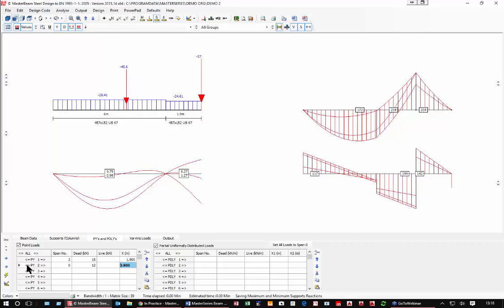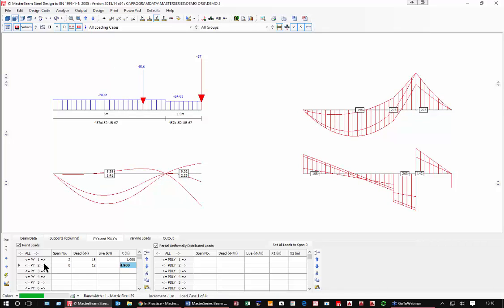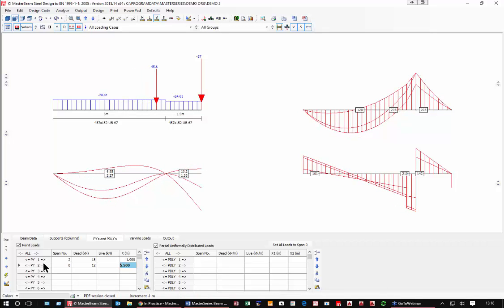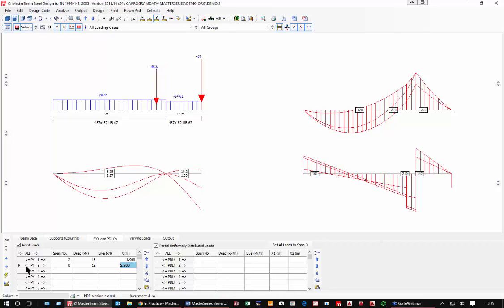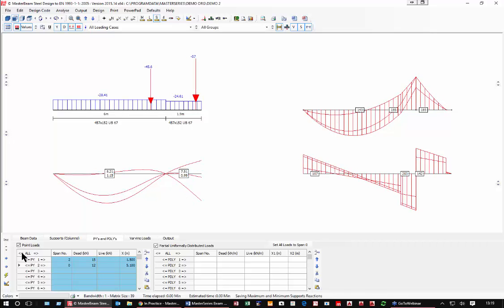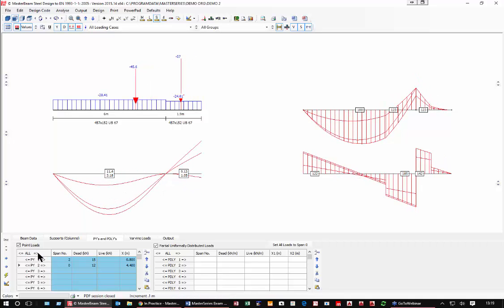So if we wanted to place this load at the position that will give us the minimum overall displacement on our left beam, I'm seeing it's going to be, well, probably around there. It's going to give us the lightest deflection. So we have this ability to move loads about on the fly and see the effect. We can also do it on all of the point loads and move them both at the same time and see what would happen.